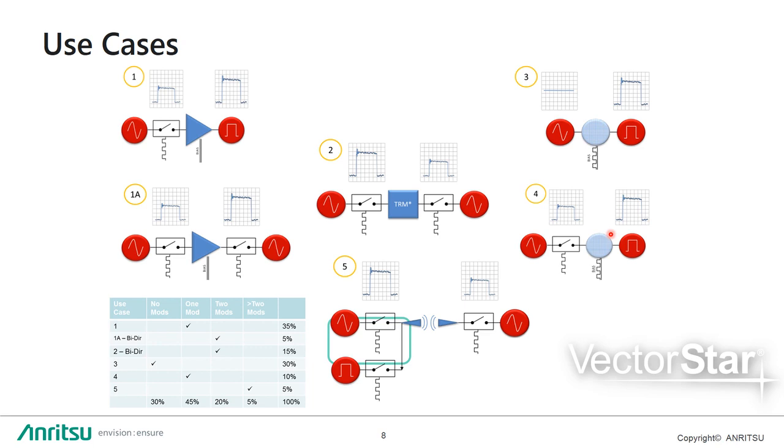The amplifier's intended end use is a pulsed application, commonly for use in a radar system component, and so the user will stimulate the device with a pulsed RF signal, as well as utilise the internal pulse generators to control the bias to the on-wafer device to compensate for the lack of a heatsink and to minimise the thermal effects, and therefore the timing between these pulses is important to ensure the RF is applied to the device while it is turned on. Normal use of the device is with a unidirectional pulse, but the user wants to include the response to a reverse direction pulse for a complete component characterization.